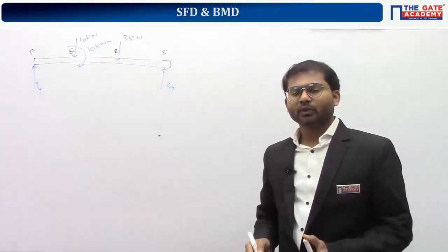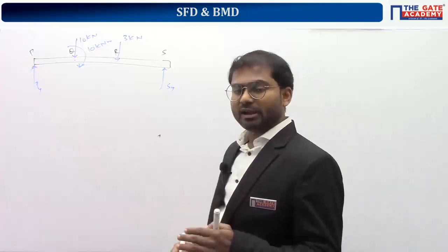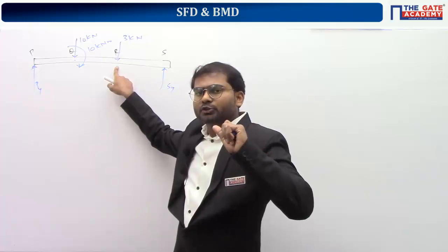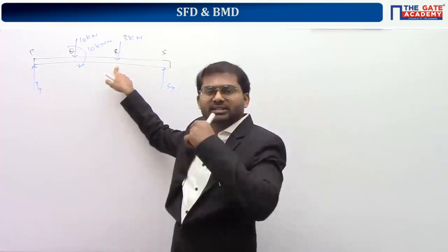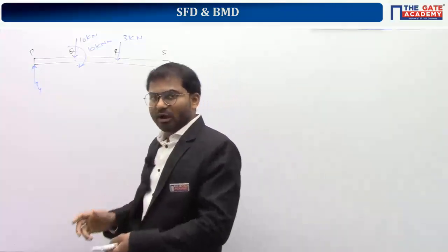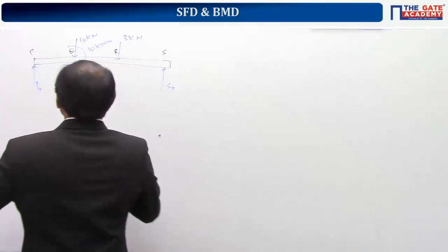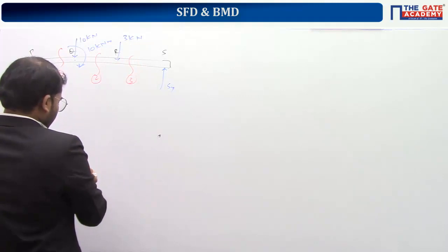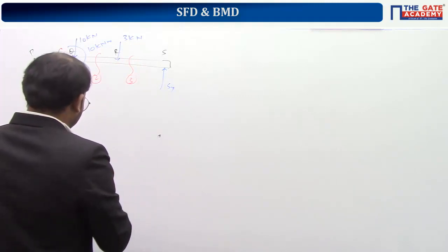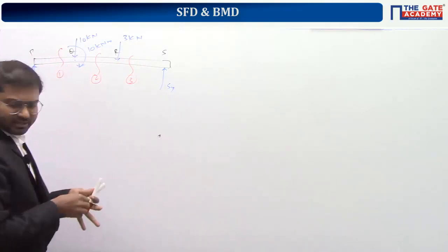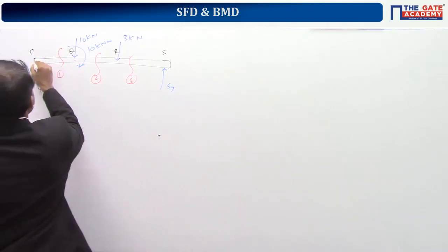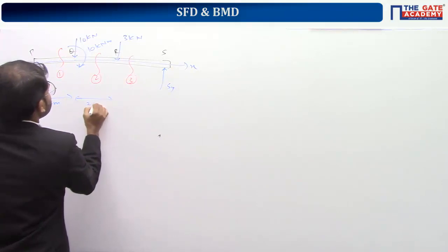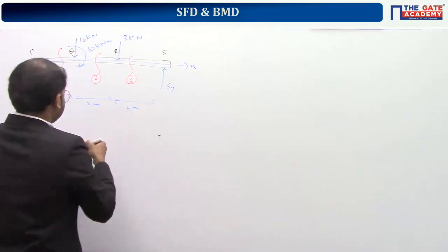That's very easy. Now in this question they're expecting us to get the value of the bending moment at location R. Here you can eliminate many unnecessary steps, because if you have to draw the whole bending moment diagram, you should do cutting thrice. Taking the x-axis, this is 2 meter, another 2 meter, and another 2 meter.